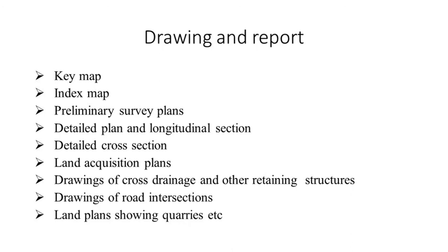And next to that we require soil and material studies. Okay, so after selection of the center line of the road, investigation of soil and other material required for the construction. That means how much material is available, what is the quantity of material available, is the material easily accessible. Okay, and the soil condition, what is the soil condition? Either it is poor soil or it is good soil. Okay, so that also you have to check in soil and material study. So in the next upcoming topic we are going to discuss the soil and material studies.